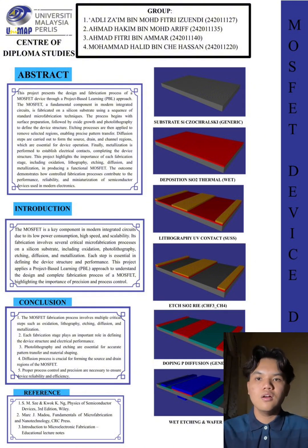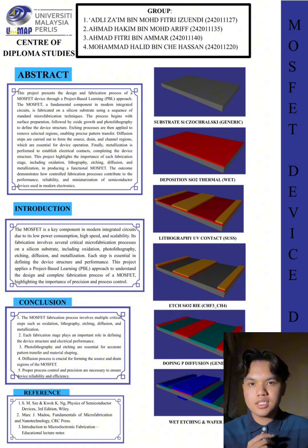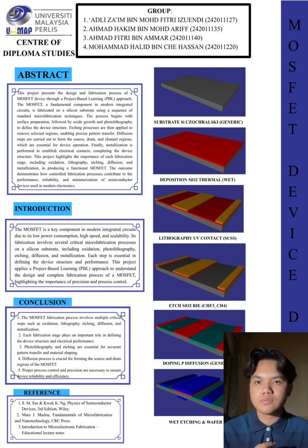fabrication. For the second lithography and etching, the process of photoresist coating, lithography, and etching is repeated again. This allows us to create more detailed patterns and open specific areas where electrical contacts will be formed later. Repeating these steps improves the precision of the device structure.